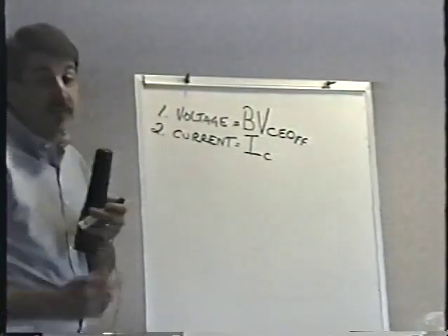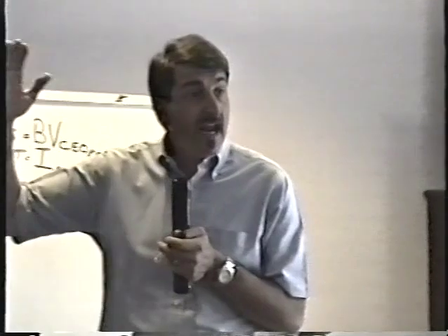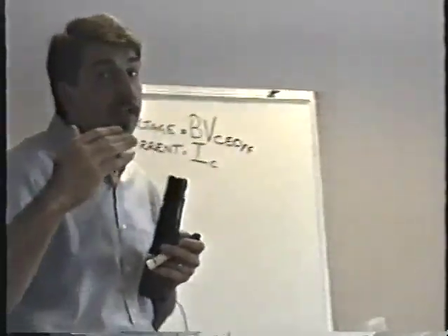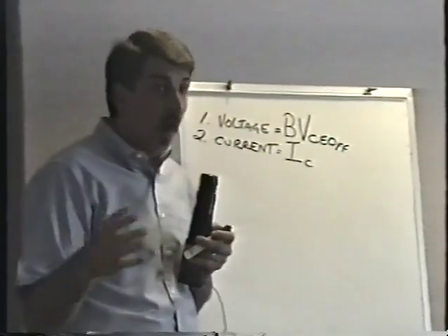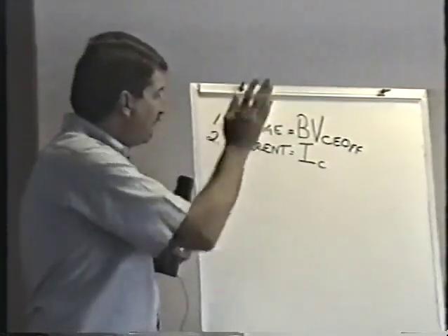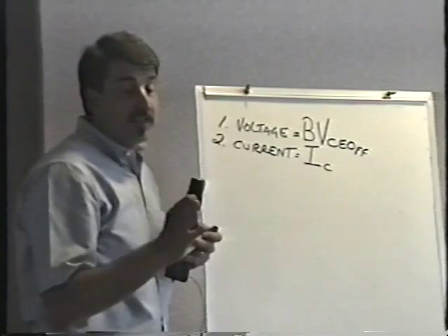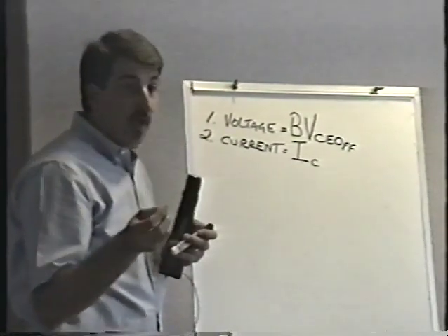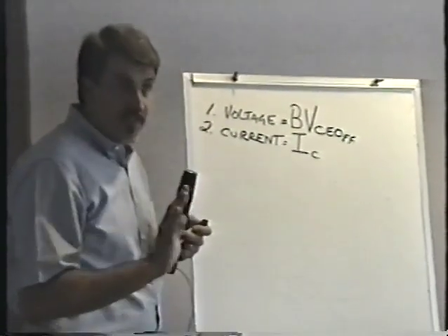Substituting transistors is exactly the same as substituting diodes. If you have a transistor and you need to get a replacement for it, you can always use a transistor of the same or higher voltage or current ratings. Always. You can go up as high as you want in voltage, you can go up as high as you want in current. All transistors work exactly the same way. The only difference is these ratings.